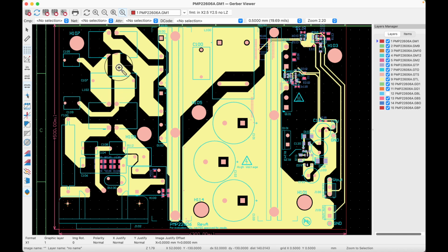But then you get these funny shapes, and sometimes we call those plane shapes. So you can see there's lots of plane shapes or some traces. So they tried to fill in the copper. Remember, the copper is free. It comes on the board. You take away where you don't want it. So yeah, use copper generously, but properly at the same time, right?